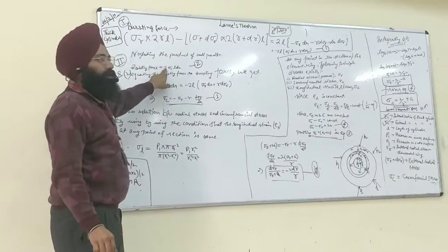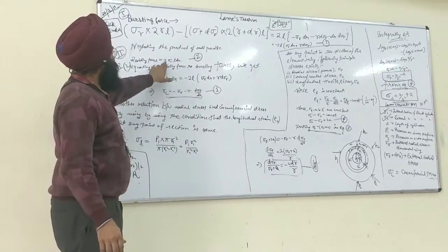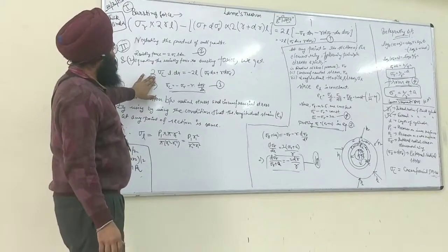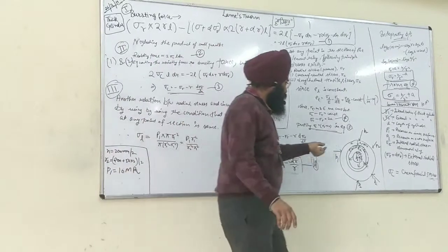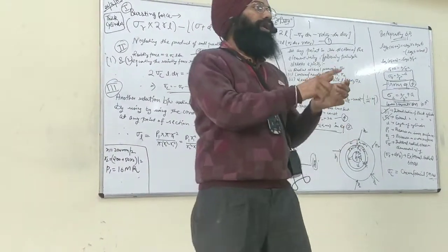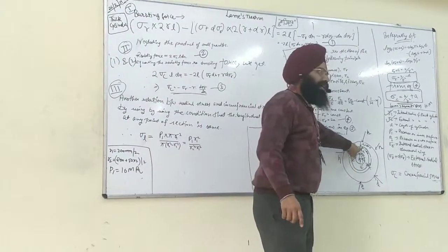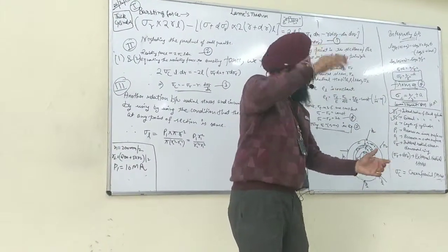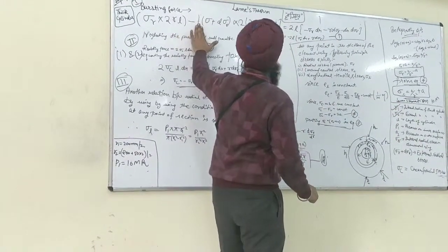Now the resisting force will be along the circumference, because the circumference is providing the resisting force. That is 2 stress C into L into dr, same. Now we again take the small section into consideration. You must note that during the bursting force, this small section was acting in the opposite direction. Bursting was from this side and this section was causing resistance. So we have taken it in the negative.